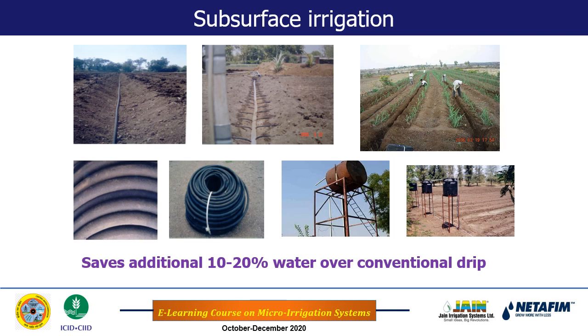The porous pipes are installed actually. Remember that these are not inline drip or subsurface drip, but porous pipes. These porous pipes are installed as I showed you in the second figure, and how a porous pipe looks, I have also shown in the bottom photographs. They are installed just like we install drip laterals into the field. These porous pipes are connected to the submain pipeline, the submain is connected to the main, and the main is connected to the overhead water tank in this case.